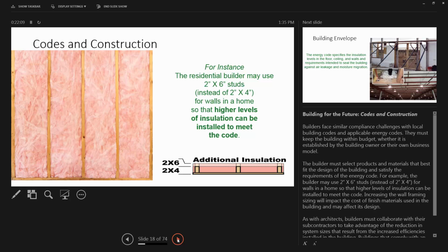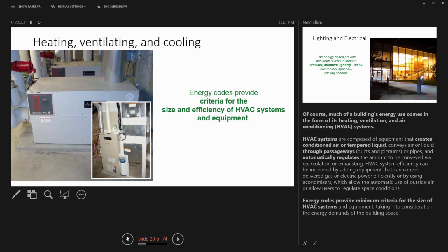We'll try different wall systems out and look at the performance of them, and you can see the difference between a 2x4 wall with fiberglass loose fill insulation versus a 2x6 wall with dense pack blown in cellulose with a much higher R value, much lower air infiltration. So we'll get to see some of those once we get further down the road.